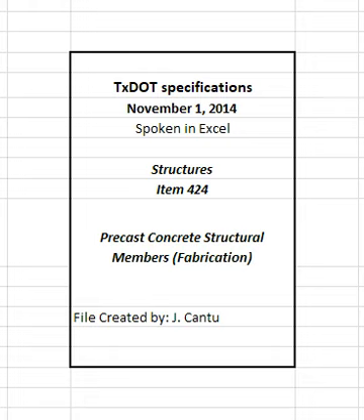4.2.2 Prestressing. Perform pre-tensioning in accordance with this item and post-tensioning in accordance with Item 426, Post-Tensioning. 4.2.2.1 Prestressing equipment. Furnish hydraulic jacks with sufficient capacity for prestressing the steel. Equip the jacks with instruments for monitoring the hydraulic pressure. Provide gauges at least 6 inches in diameter and with means to prevent the gauge pointer from fluctuating. Electronic pressure transducers with digital indicators may be used.